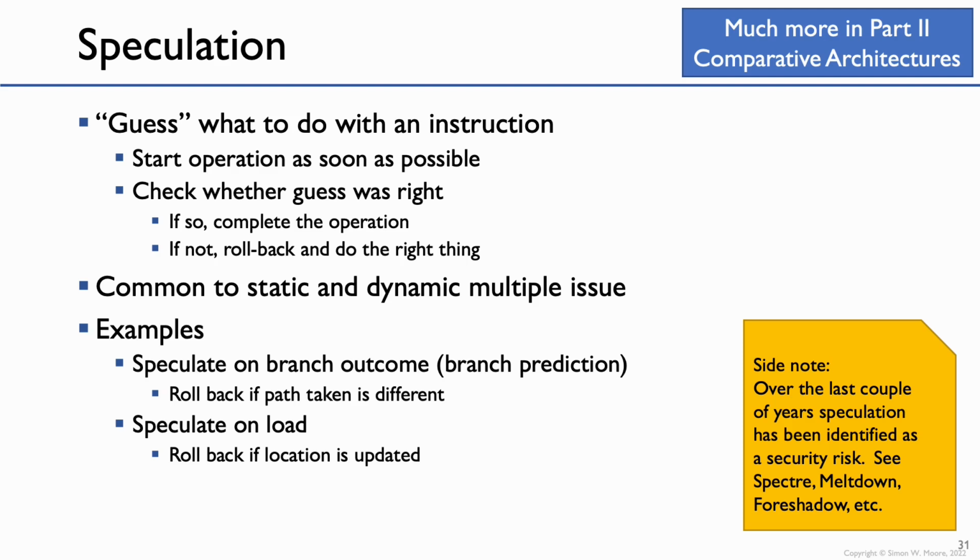An example of this might be writing a value to a bit of memory and causing that memory location to be read into the cache, and then you can check the cache timing on a subsequent load, and this can actually be used to leak information.